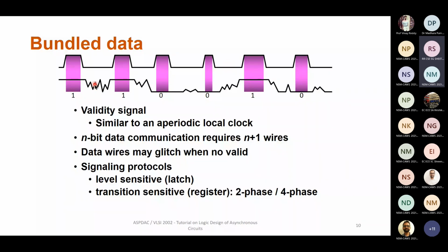So my combinational logic itself can have any timing, but unlike self-timed circuits, which give average performance, I will talk a little bit about that aspect in a moment. The generation of the valid signal is now required because you have to study the combinational circuit and find out how much time it takes. For example, let us say the first combinational logic takes 500 picoseconds. Then I can generate this valid signal after 500 picoseconds.